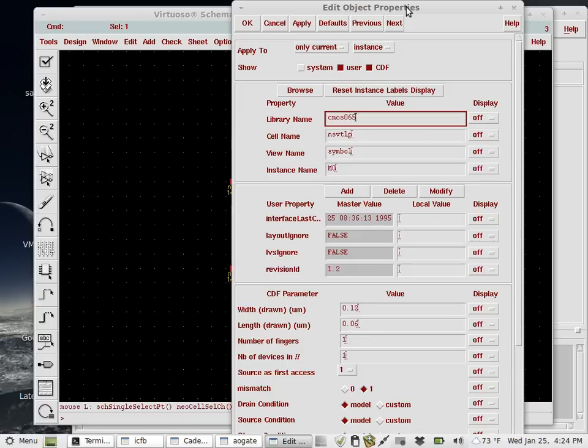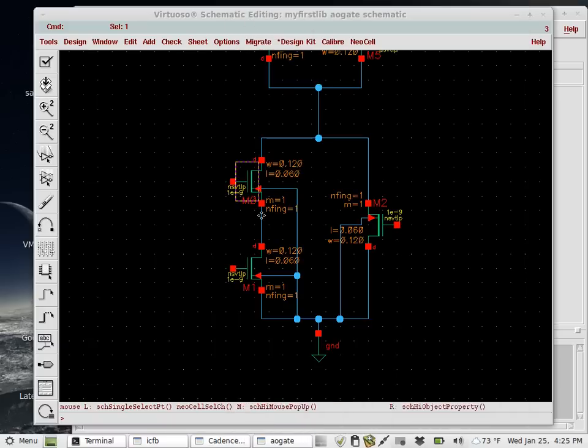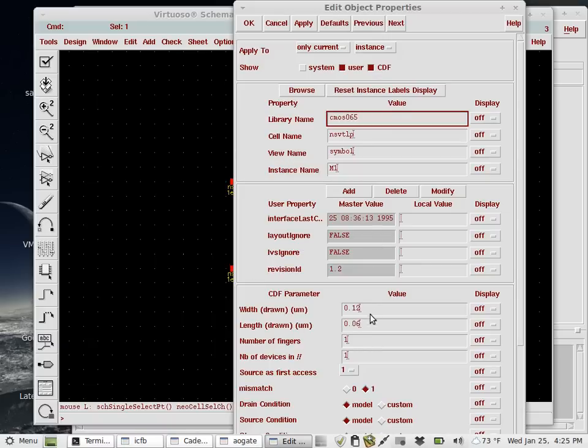Okay. So the default width here is of course 120 nanometer. By the way, here it's supposed to be 65 nanometer, but for some reason they chose 60 nanometer for the length. I don't know why. Maybe they round or truncate after, perhaps rounded by 10 or something. But I wanted to make them double, so I make this 24 and I make this 24.